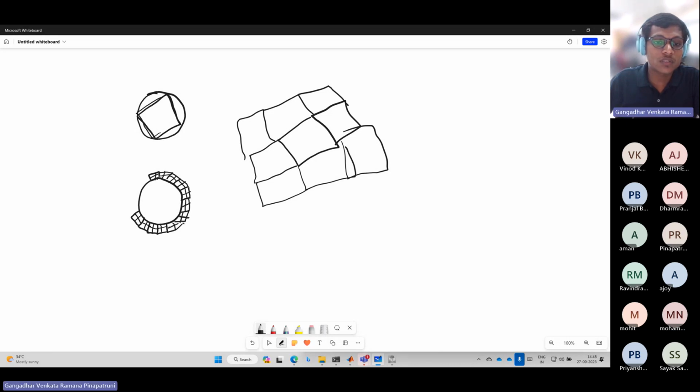Where external to this, it can keep those cells much larger. So these capabilities are all predefined in the ANSYS software. That's why it is a commercial one. So it has the capability to understand what our required component is. If a cylinder is your required component, there it creates a small mesh size, and far away from the cell, it can create coarse cell size where it is not required to understand the flow physics.